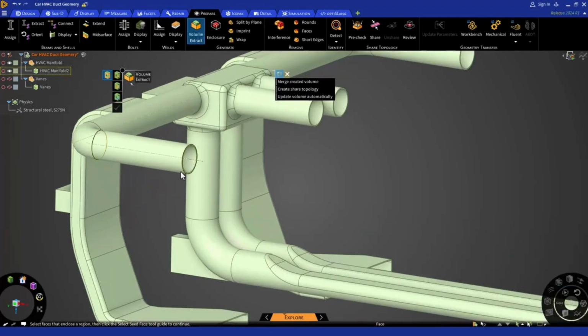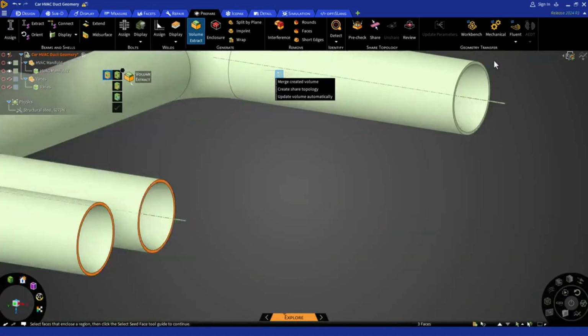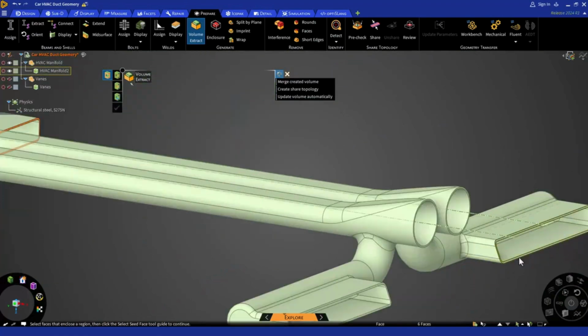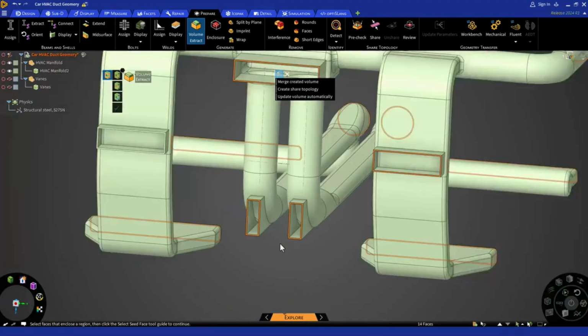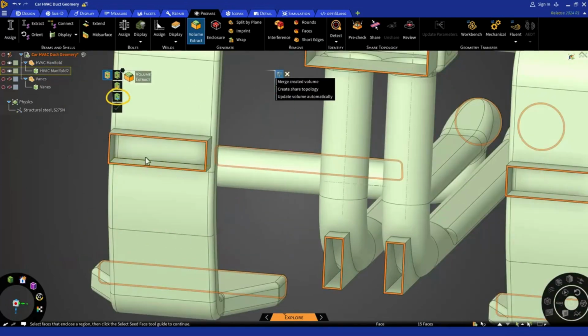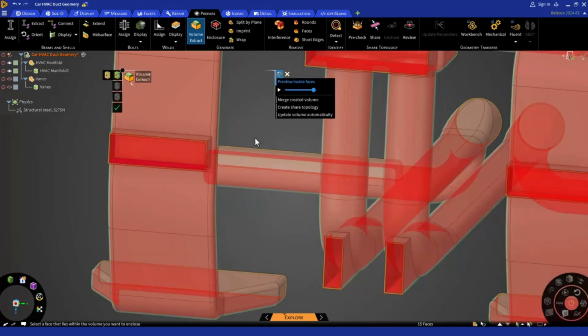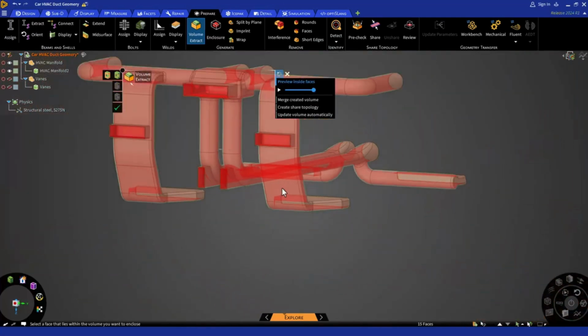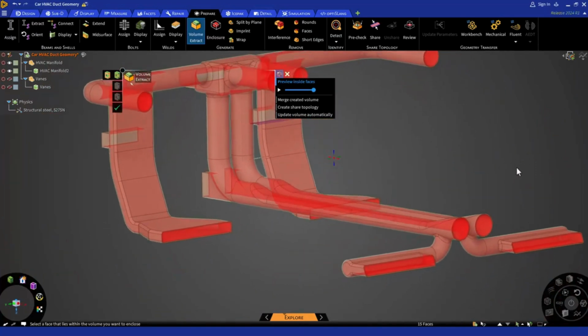Select all the faces in which our fluid volume is going to be enclosed. And then select a seed face, which is one of the internal faces. Let's preview the fluid volume again using Preview Inside Faces from the right side of the heads-up display, or HUD, before hitting the check mark. Here you can see that there are no leaks and everything is enclosed within the solid volume.